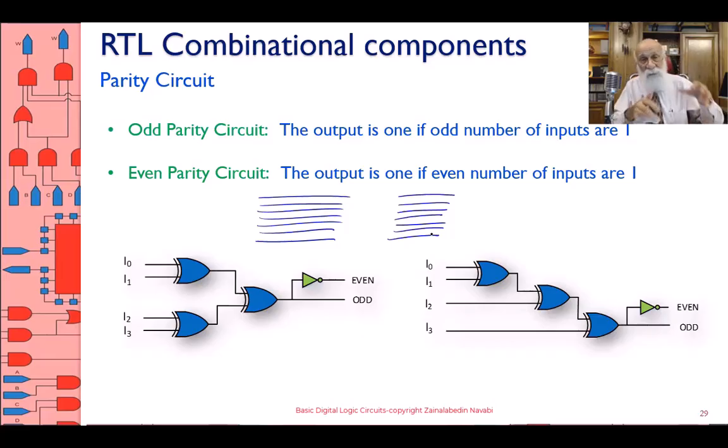Okay, one way of duplicating it is to have all these 8 lines repeated. But you don't really want to do that, because that means a lot of hardware that you have to repeat. The reason you want to do the duplication is because if noise happens along the way, you'll be able to at least detect it. Not necessarily correct it, but at least detect it. So what you do is you put a function here that is a function of all these 7 inputs.